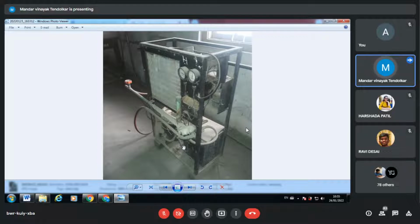In that particular video, what was shown is like a solenoid control valve. Our setup is 100 years old, so it's a simple copper capillary. So this is one type of expansion device. Nowadays, it is much more advanced, so you can use a solenoid control valve and many other types, like the thermostatic expansion valve. In the next experiment, I will show you the thermostatic expansion valve.